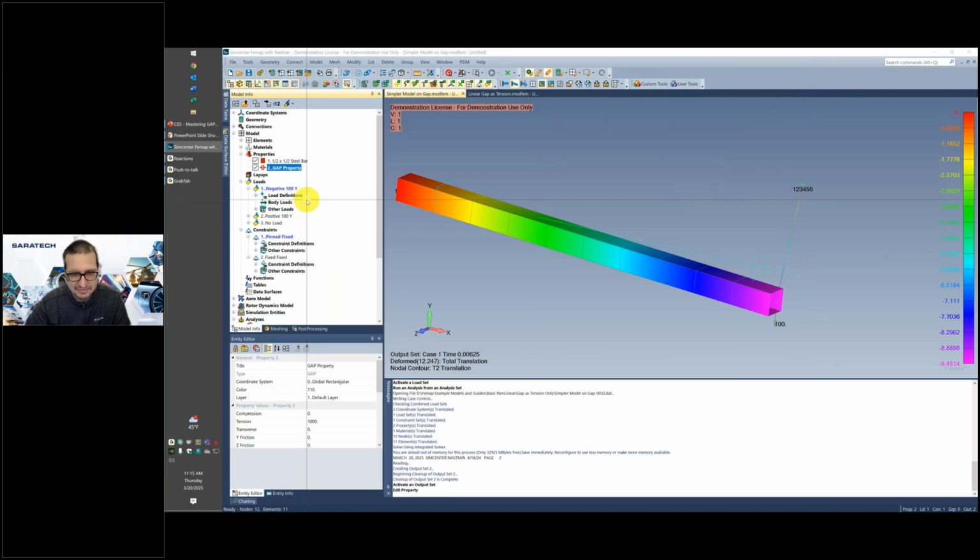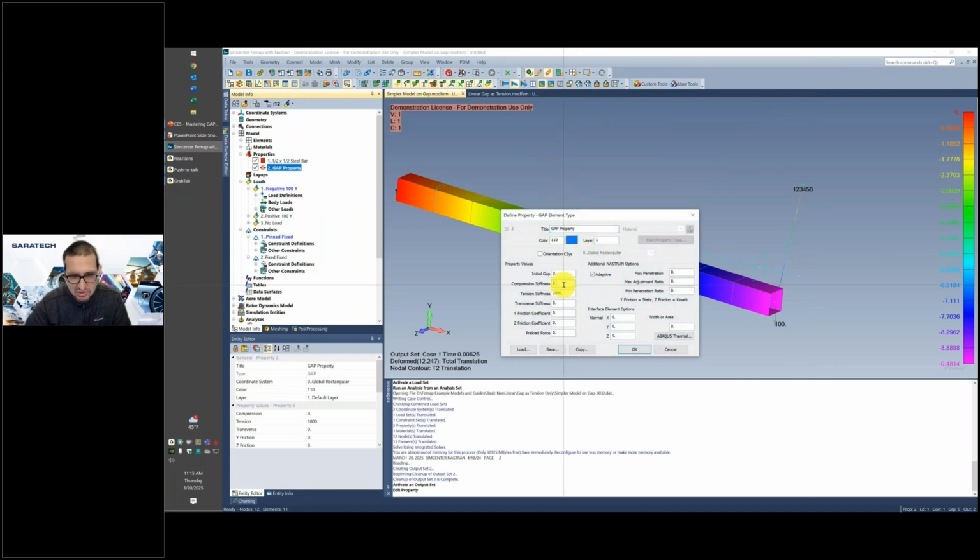There is kind of a cheat to this. If I put a small compression stiffness in here, the analysis will run. Now, what I found through testing is this compression stiffness is kind of relative to this tension stiffness. If this value was larger, I would need to use a slightly larger one here. So if my stiffness happened to be 100,000, I'd have to up this to 0.1. Now the ratio of these two doesn't seem to be very fixed. If I was running this at like 10, you would think if I set this to this value here, it would function, but it does not.